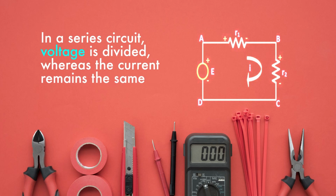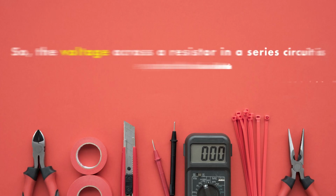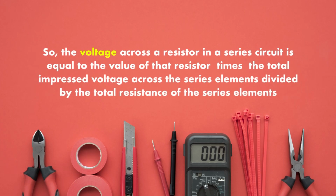The voltage division rule can be understood by considering the series circuit shown in the figure. In a series circuit, the voltage is divided whereas the current remains the same. So E1 can be written as total voltage E multiplied by the resistance R1 upon resistance R1 plus R2. Similarly, you can calculate the voltage E2, that is voltage across terminal BC, equal to total voltage E multiplied by resistance R2 upon total resistance connected in series, that is R1 plus R2. So the voltage across a resistor in a series circuit is equal to the value of that resistor times the total impressed voltage across the series elements divided by the total resistance of the series elements.